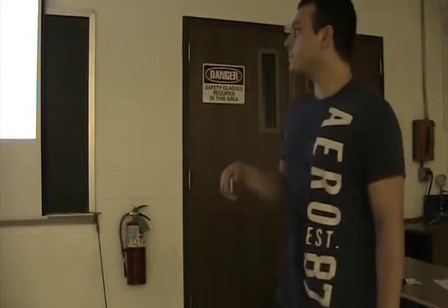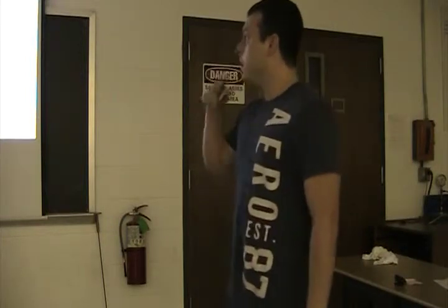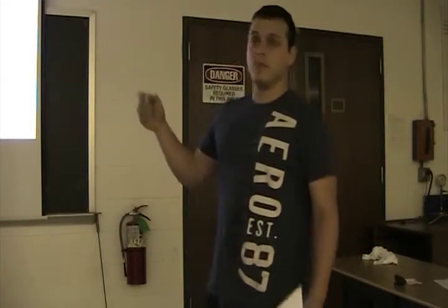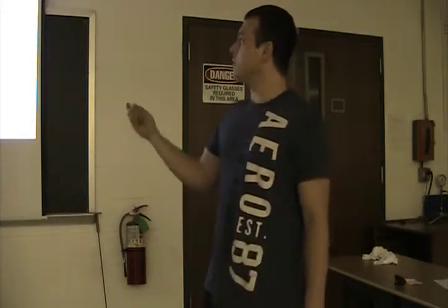All right, there are two different types. You have a subsonic ejector. In a subsonic ejector, you have low velocity, high pressure steam coming in, and in the converging nozzle the area decreases, so it accelerates the velocity of the steam and also lowers the pressure. Your lowest pressure is going to be at the throat, which is the smallest cross-sectional area of the CD nozzle.